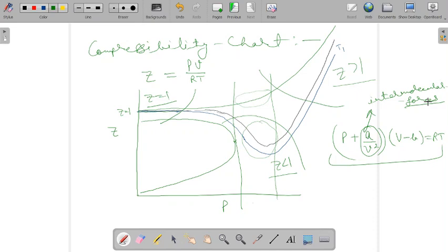And another important point which we consider in ideal gas behavior is that the volume of the gas molecule is negligible in comparison to the overall volume of the system. Okay, so here this term is to account for the volume of the molecule. Okay, is this one clear? In the majority of compressible flow analysis, we will be finding high enough temperatures and moderate pressure. That's why the majority of compressible flow analysis can be performed by idealizing the gas behavior, by considering a thermally perfect gas. Is this point clear?